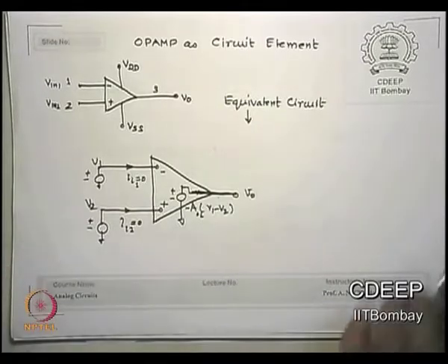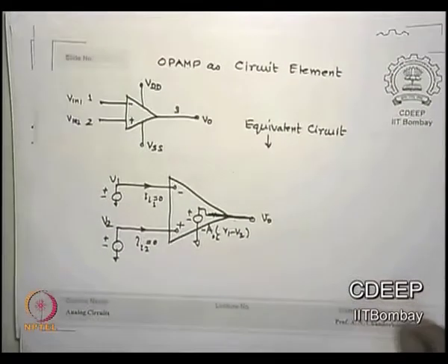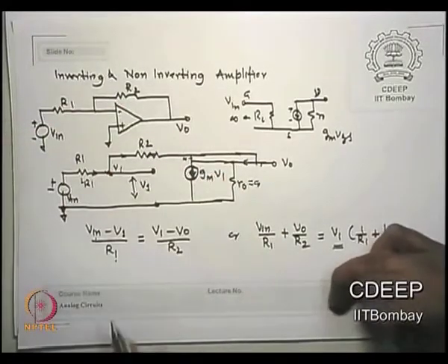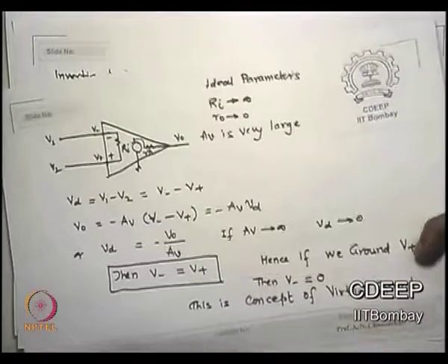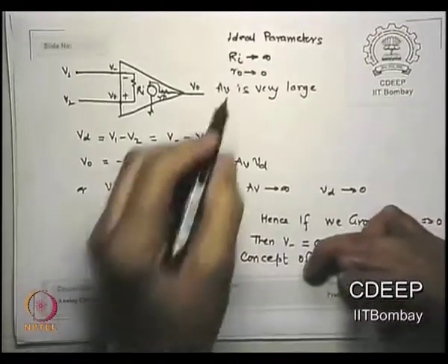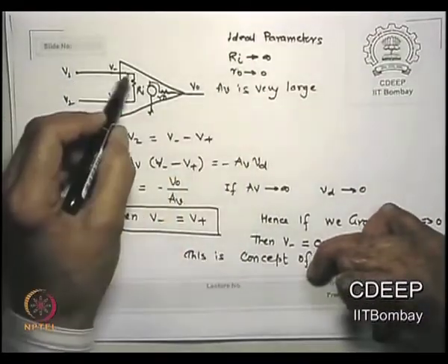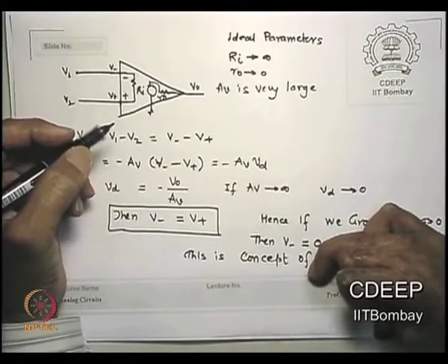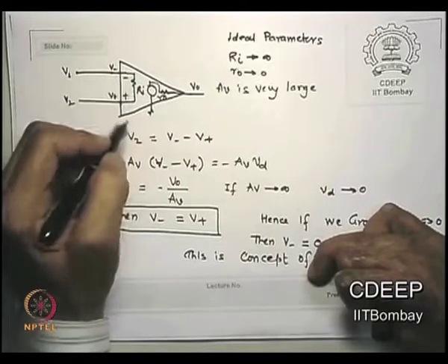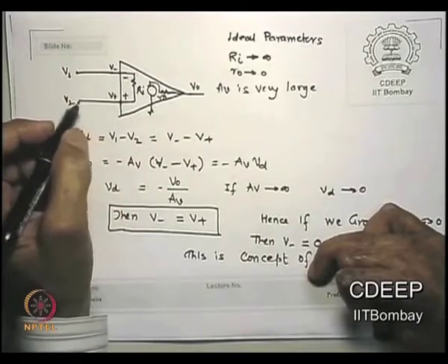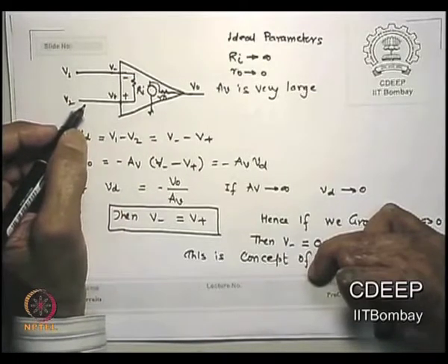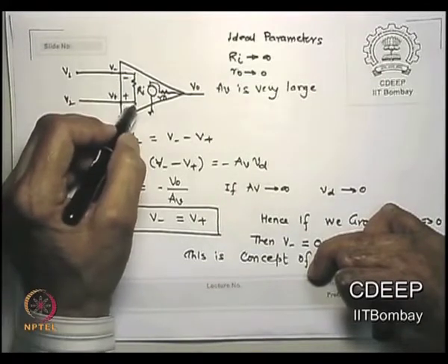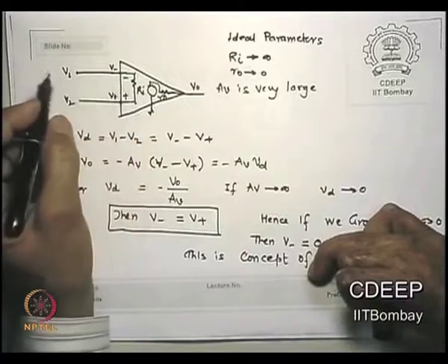Okay. Now we will prove this. Why did I say so? If you see this amplifier once, okay, let us do this first. If Ri is infinity, what does infinity mean? Essentially an open circuit, but really there is nothing called infinity. So that means there will be a very large resistance connected between this and this, is that correct? So how much will be the current?